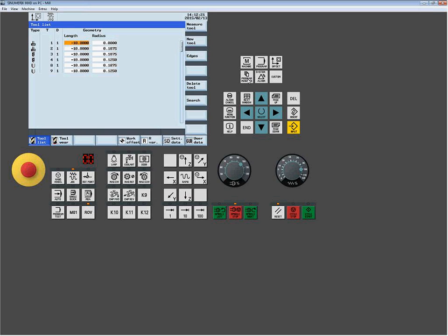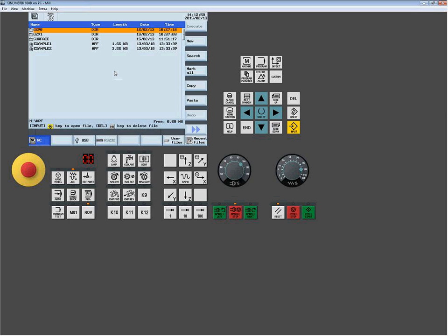Right. From there, what I want to do is transition over to my Program Manager section. Now, navigating through the different screens with this keypad on the right side of the display, you're going to see my mouse kind of hovering over it. With that, I can navigate back to the machine area. That's my jog screen by hitting machine. I go right to whatever program was last edited with this program button, or I can select the program manager button, and that can get me to the area where my part programs exist.